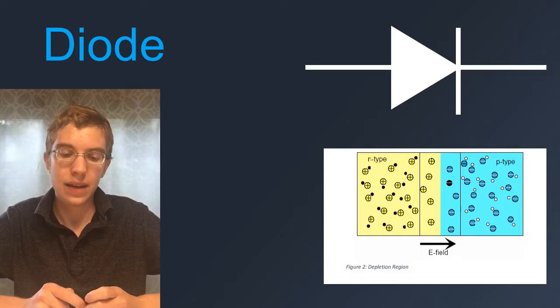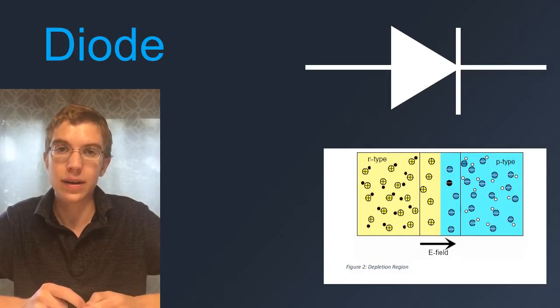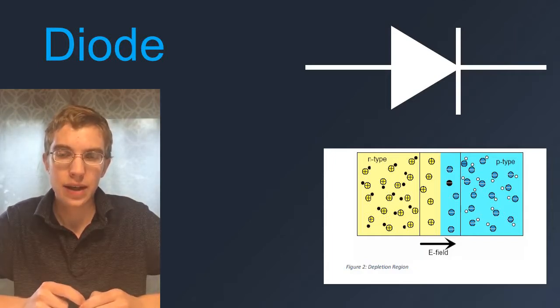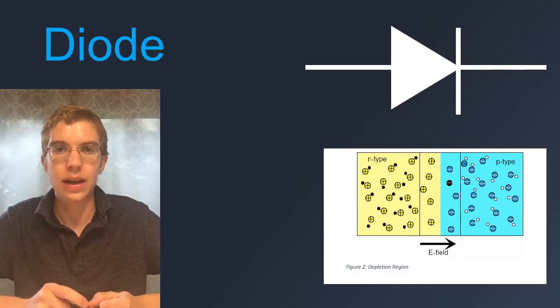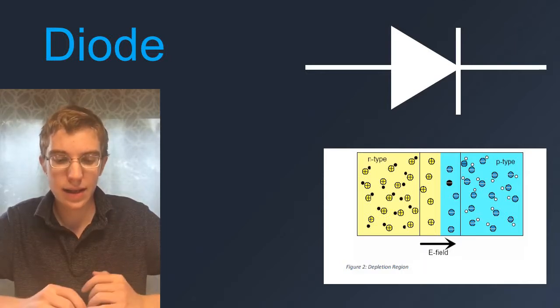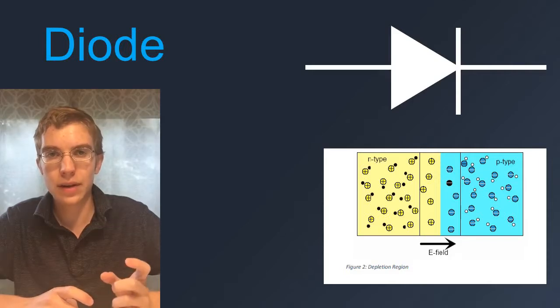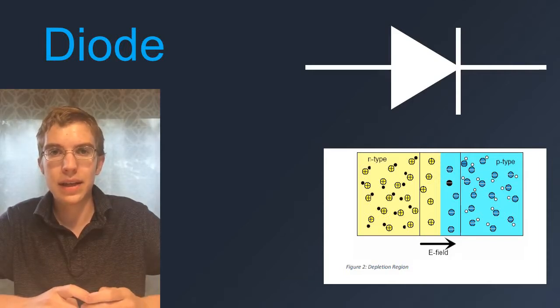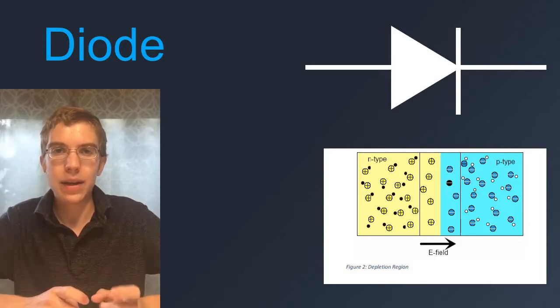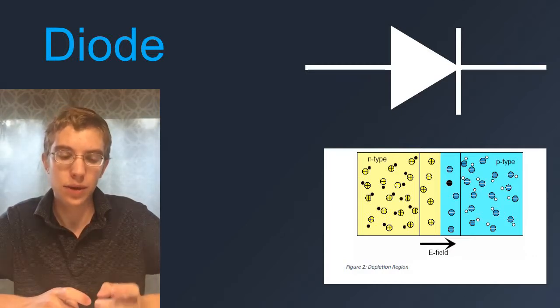going to be in. If the voltage across the diode is less than the threshold voltage, the electric field in the depletion region is going to prevent current from flowing, and if it's greater than or equal to, the diode is going to begin to turn on. In the case of the full wave rectifier, when the rectifier itself is on, there need to be two diodes on, and those will be in series. So at minimum, in order for the rectifier to be on, the source will need to have at least a difference of twice the threshold voltage.